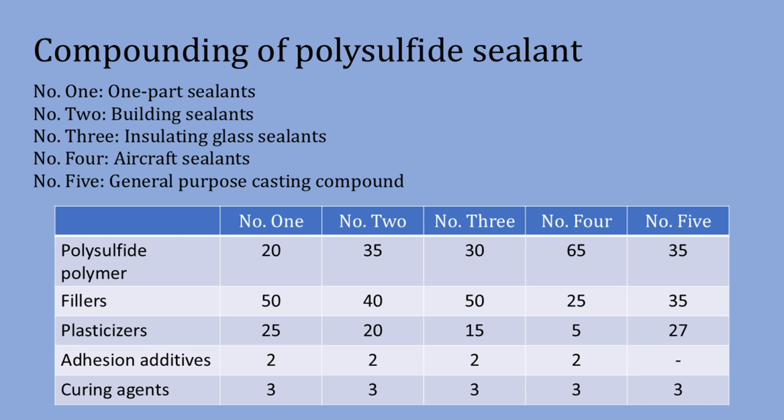The unique molecular structure of polysulfides naturally imparts resistance to ultraviolet light and oxidative degradation. Still, the extent of this resistance is heavily influenced by the formulation details, especially the polymer content. There is extensive evidence showing that the longevity and durability of polysulfide sealants across different applications are closely related to how much polymer is present. This slide focuses on examining various formulations by exploring the component combinations used in polysulfide sealant compounds.